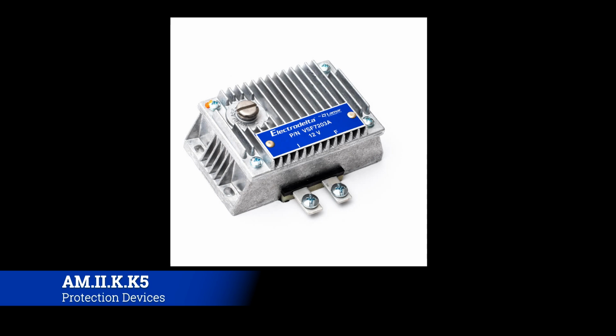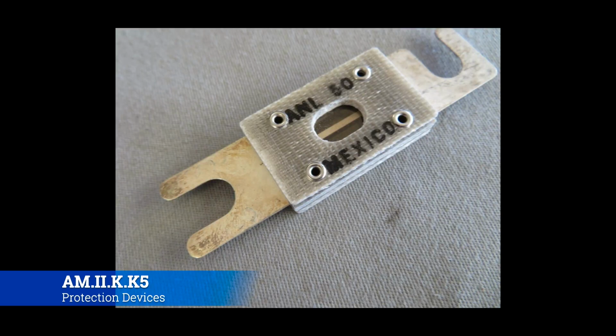All right, the carbon pile, while it's kind of cool that it naturally wants to regulate voltage, has largely been replaced. You don't really see those anymore. The next one up in sophistication will be the 3-unit regulator. That's a picture of the one that we saw earlier. You have 3 relays that react as needed to the detected situation, and they open and close to help manage the level of voltage, or to regulate the voltage would be the better way to say it. Okay, so current limiters are something that you'll get really familiar with because they are actually on the Lear.